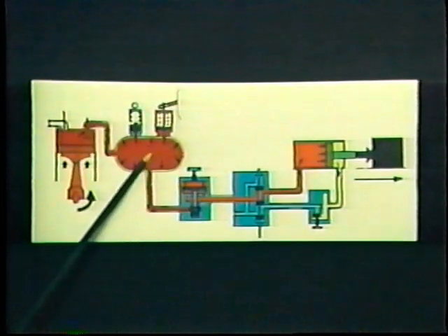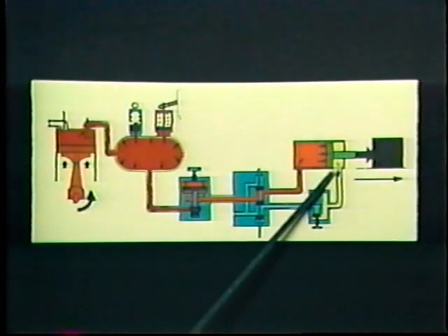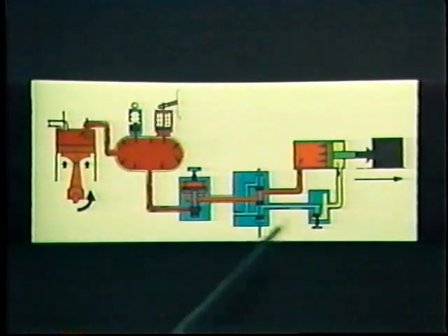Red indicates supply pressure. Orange can mean either reduced pressure or pilot pressure. Yellow indicates metered flow. And blue stands for exhaust. When the air is colored violet, it will indicate an area of intensified pressure. These colors are the ones accepted as the international standard.